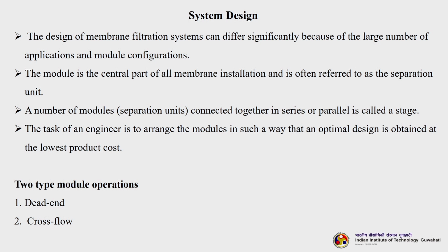So, now let us talk about the system design. The design of membrane filtration systems can differ significantly because of the large number of applications and module configurations. So, there is no thumb rule. Everything depends upon what your requirement is and what is available with you. The module is the central part of all membrane installations and is often referred to as the separation unit.